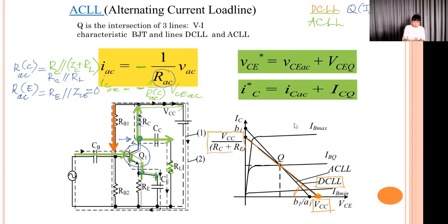The second point is the value VCC divided by RC plus RE. You should learn this by heart and solve this question very quickly.